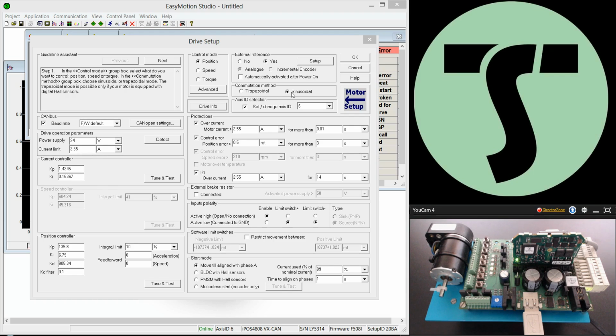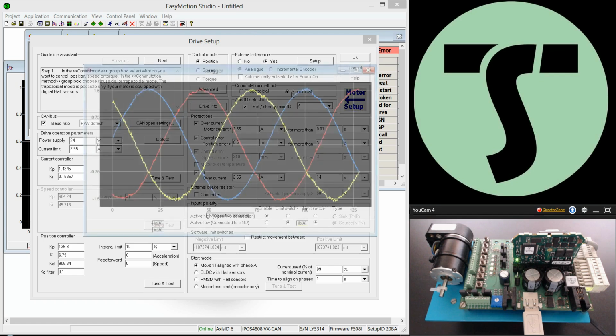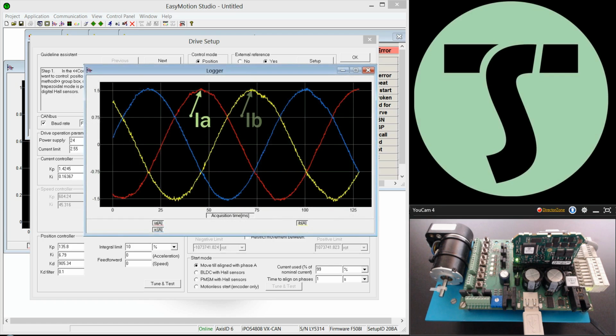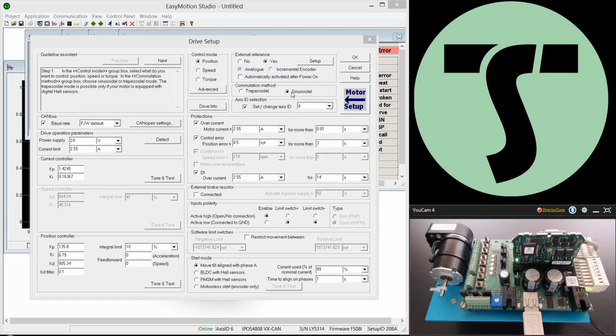The sinusoidal mode is the default one and the more complex mode, where the motor is controlled as BLAC, brushless AC, using field-oriented vector control algorithms with the help of the encoder. The currents are now sinusoidal and all three phases are supplied at the same time. This mode offers smoother operation than the trapezoidal mode, especially at low speeds.